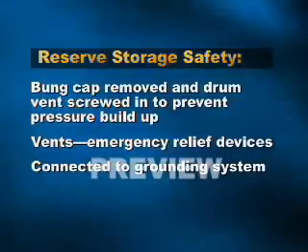For reserve storage safety, as soon as a drum is unloaded, the bung cap should be removed and a drum vent screwed in. This prevents buildup if the drum is exposed to heat. Proper vents also incorporate emergency relief devices, which blow out under extreme pressure. Drums also should be connected to a grounding system. This eliminates static electrical buildup when dispensing from the drum.